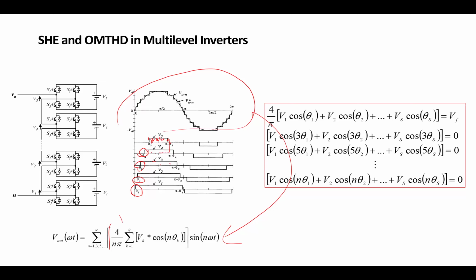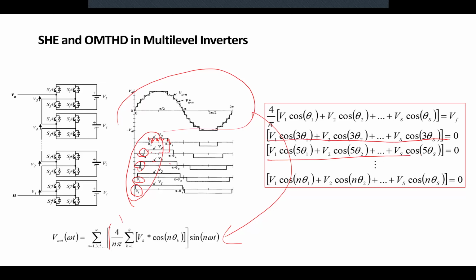You run the code and calculate what should be the frequency and phases of my reference signals that go to the PWM, how I could decide about these thetas, the time that each level gets on and off, in a way that I could make these harmonics equal to 0, and keep my main component, the voltage that I want.